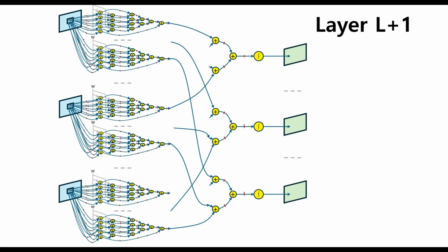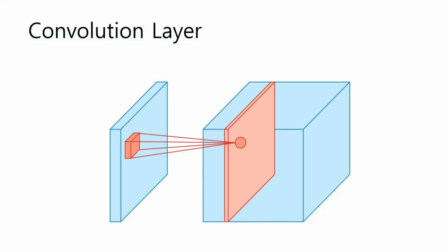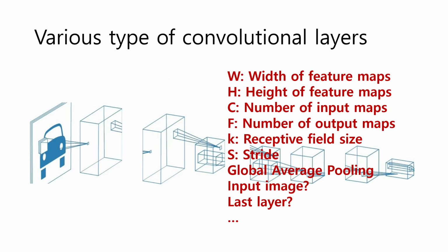Fourth, although the computational circuit is fixed as a hardware circuit, it should be able to execute various types of algorithms with the same circuit, and each algorithm consists of a large number of convolutional layers, each with different computational characteristics, such as the size of input-output feature maps, k-value, stride and activation function, global average pooling, etc. Therefore, the system needs a mechanism that can process such computational requirements in an orderly manner.